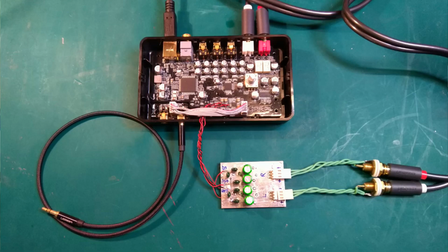Okay, time for the moment of truth. See if this actually makes any improvement to the performance. So the new front end has been soldered into the original board here, and I connected the line out to the new board here. This is of course single-ended, and this is a balanced input. So the negative part of the positive-negative is just connected to ground, and then the signal here is just connected to positive.